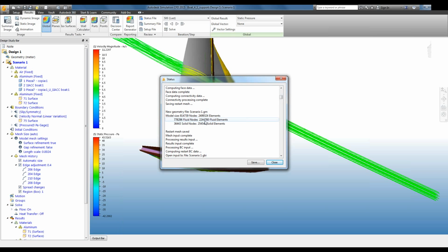resolution I wanted. Keep in mind, too, had I actually meshed the sails as volumes, or actually suppressed the sails as volumes, I would have been able to use the mesh adaptation. So somebody that's maybe doing the flow over a car would leverage the mesh adaptation, in which case you would start off with a mesh even less intense than this and let it do its thing, where it's adding the elements exactly where it needs them instead of wasting elements where you don't need them.